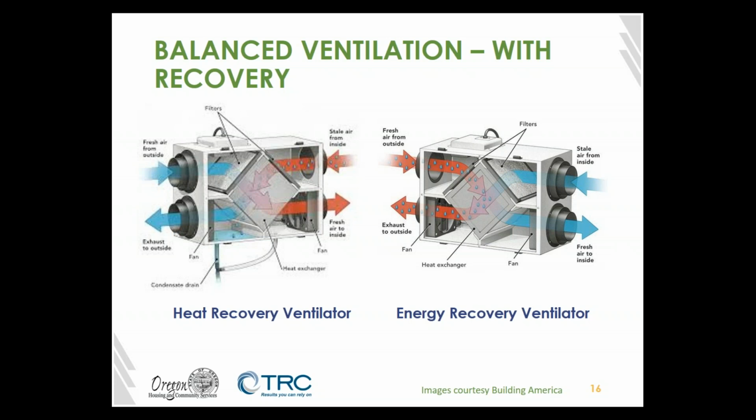It brings it through, and the sensible energy also gets maintained, and sensible is the term reflecting the amount of energy just in the temperature of the air. So energy recovery has a little bit more expensive engineering behind it to do that transfer of the moisture, but you also get more savings because you're saving the heat load that's in there, and you probably also don't necessarily need to run a humidifier on the inside so it doesn't dry out, because you're able to keep and maintain some of that moisture indoors.